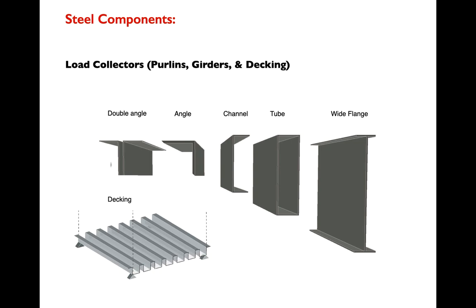And if you look at these, you can see that we have wide flange shapes that have the kind of best possible shape for bending: flanges that take the compression and tensile elements of that bending, and then a web between those that separates those and takes the shear that we get from the tendency of those flanges to sort of slide relative to one another.